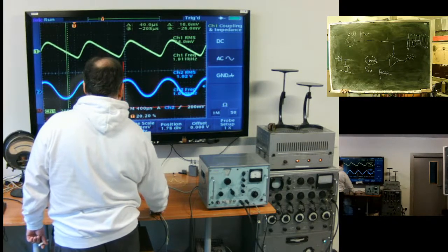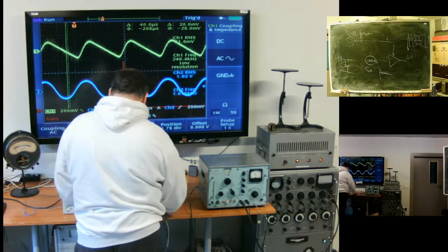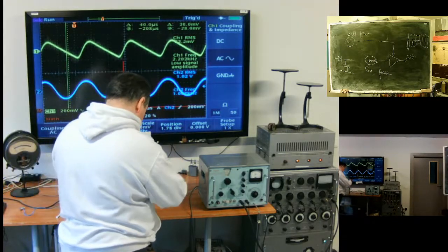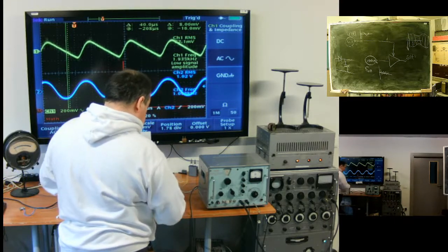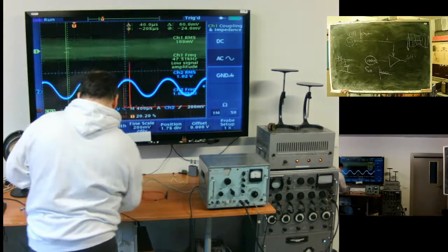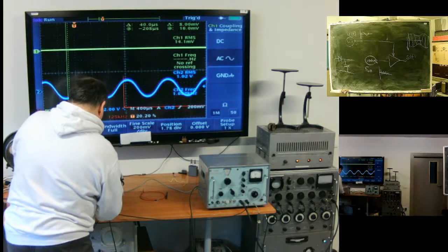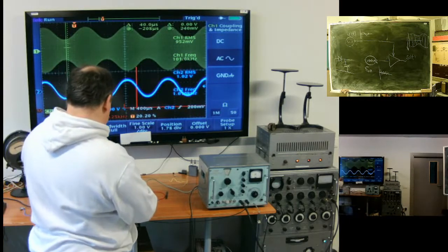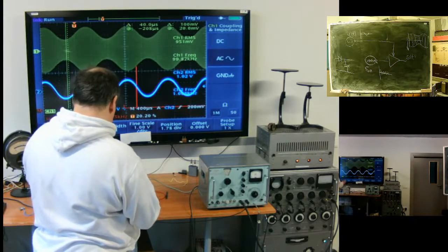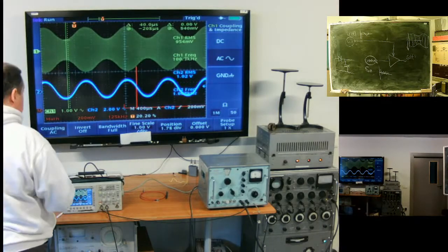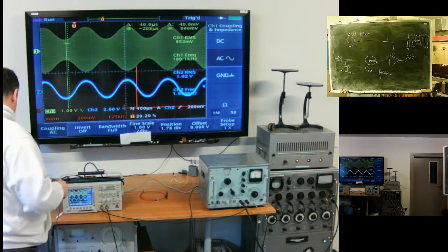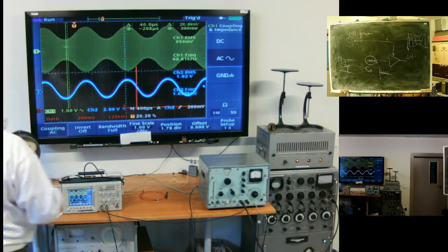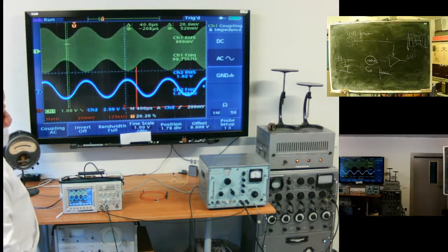Something needs to be filtered. Okay, I'll switch back. Higher quality can be achieved with the help of a so-called synchronous detector. The signal is multiplied with the signal of a local generator, synchronized with the carrier. Okay, it's not so important.